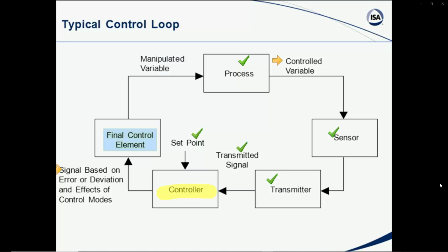The most important thing is that a corrective signal is generated and applied to some final control element, be it a control valve or a regulator, speed control on a conveyor, or whatever this might be. It is the final control element that manipulates some input variable, input quantity.